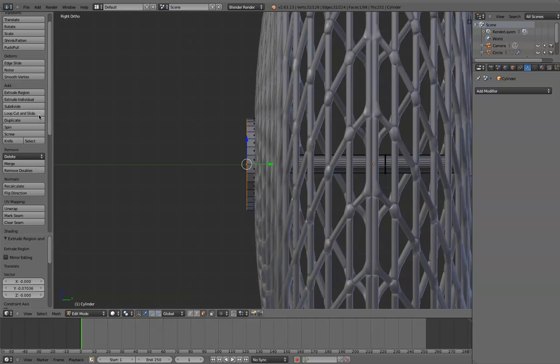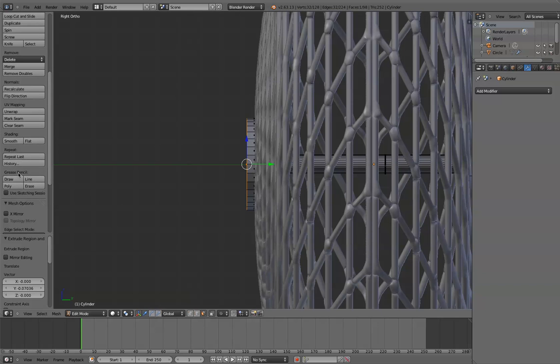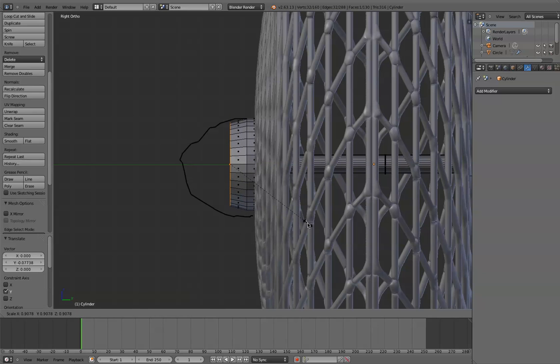So I'm going to go over to my grease pencil and draw a rough shape, that's kind of the shape we want. So I'm going to extrude, drag it out, scale it down, make an extrusion, out, scale it down, bring that back a little bit, extrude it, scale it down, drag it out. It doesn't really matter which way around you do those things.